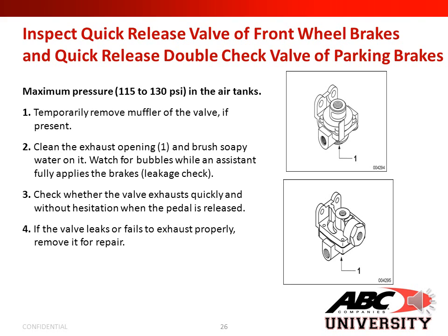Step 1. Temporarily remove the muffler of the valve if present. Step 2. Check the exhaust opening, number 1, and brush soapy water on it. Watch for bubbles while an assistant fully applies the brakes. Step 3. Check whether the valve exhausts quickly and without hesitation when the pedal is released. If the valve leaks or fails to exhaust, properly remove it for repair.